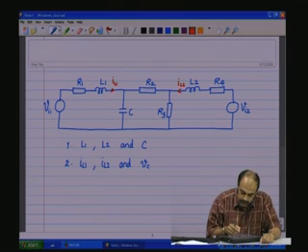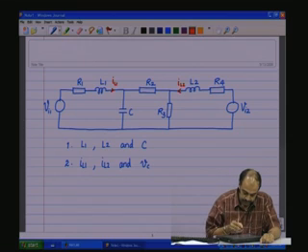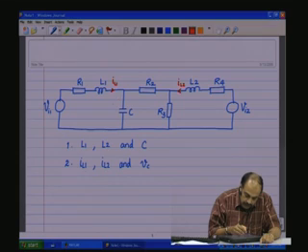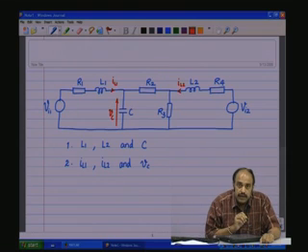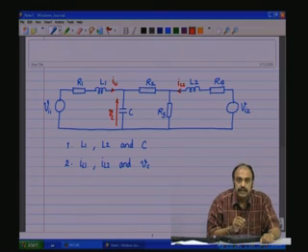Notice that I have put an arrow direction for the current flow here. It could as well be the other direction, no issues there. The sign will automatically get changed in the equation and you will not face any problems as such. Now, the third state variable is the voltage across the C, that is VC. So, now we have the state variables, the input variables and the parameters all listed on the circuit, and therefore we should be able to obtain the state equations.